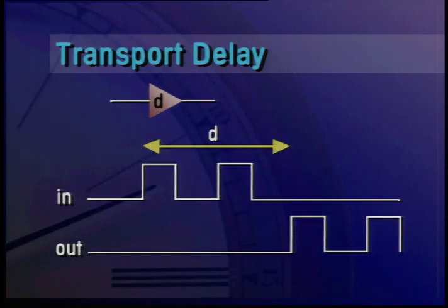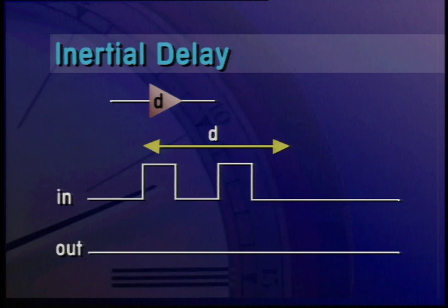The interesting thing about this is that transport delay requires dynamic event block allocation. That is, there can be an unbounded number of events associated with a single output of a gate that are scheduled at one time. And in fact, you can't determine the maximum number at compile time. Using the inertial delay model, however, causes the pulse to be swallowed, so it does not appear on the gate output. With inertial delay, there is only one event scheduled.